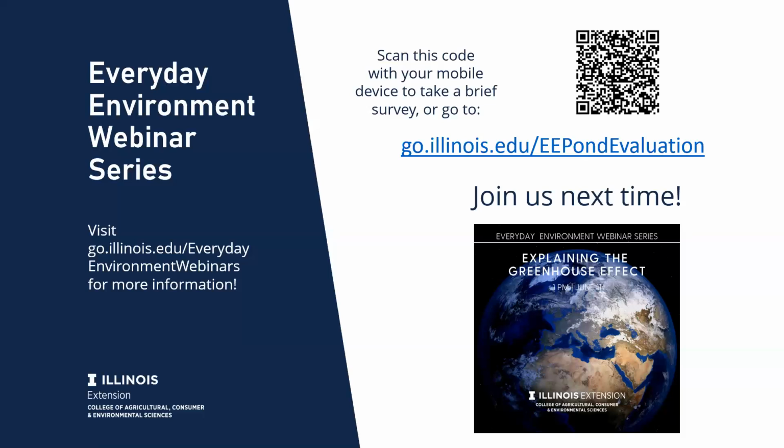You do not want, and that's something I didn't cover on the maintenance side, trees, woody brush, anything that's going to have a lot of large, deep-reaching roots, because they will basically damage the dam. They'll hurt the integrity of the dam while they're growing, because they have the potential to spread things and push. If a root gets in between a couple of rocks, some of those larger roots will actually move the rocks apart. And if the tree dies, then as that root decays and shrinks back, you've got an open pathway through there. So anything that causes a hole, burrowing crawdads, any of your burrowing animals, and trees are something you want to keep away from the structure.